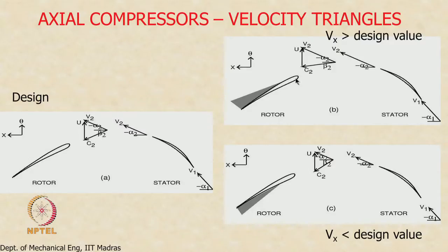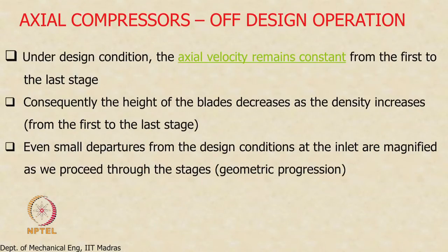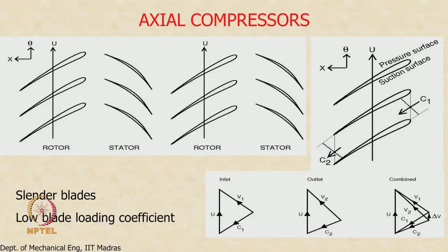So, that means the flow is incident like this upon the blade, it is not incident tangentially, which means that you can see that the flow will go this way, and there is going to be a region of separated flow on the suction side of the blade. This I think is what we call the suction side, correct. Let me just check that quickly. Yes, I am sorry, that is the pressure surface.